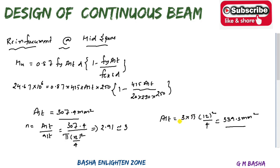But in the entire span you can select the higher moment, and for that you have to provide, and the entire beam will also be sufficient. So here we are providing 3 bars of 12 dia. So area of the steel provided will be 339.3 mm square. Without calculating this one, for this moment you can opt for the previous one also, okay, 4 bars of 12 dia, area of the steel will be 450 also, no problem.